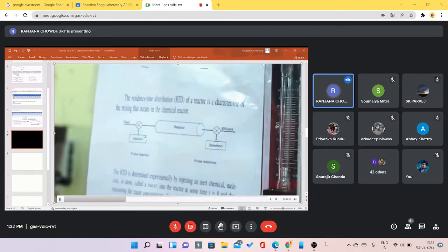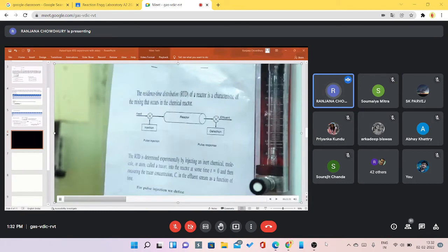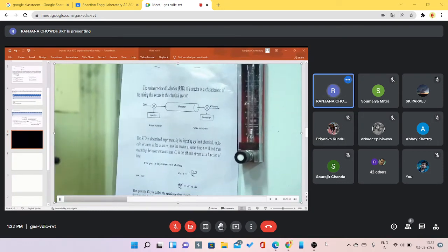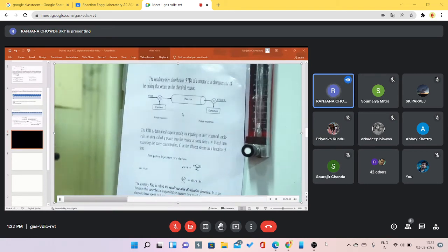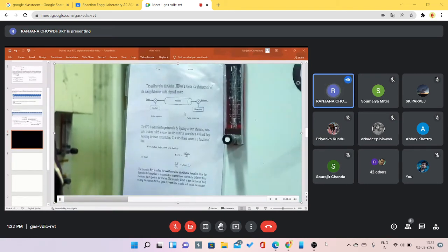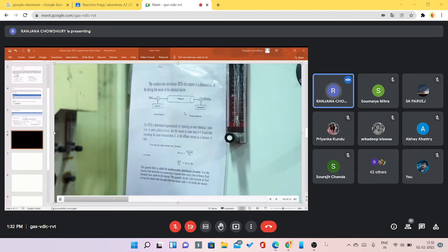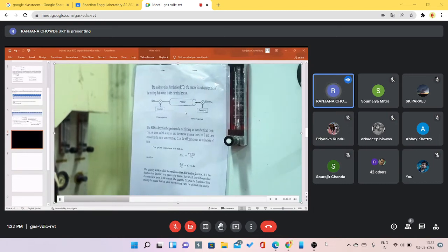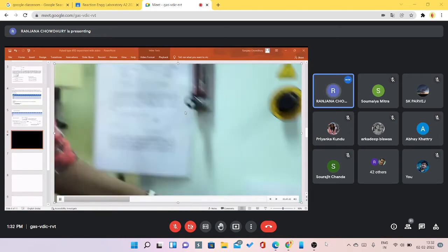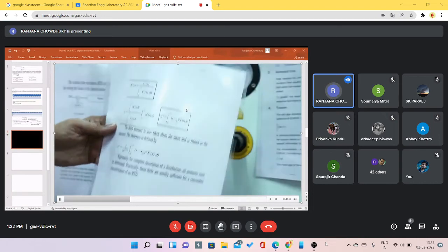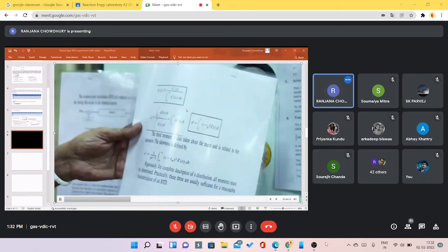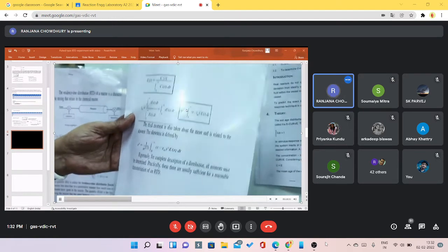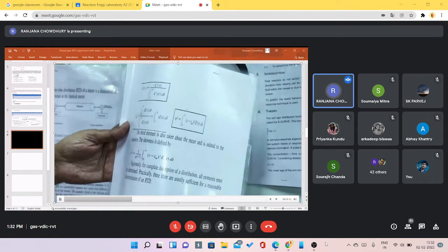This is actually the equation. E(t) is actually v C(t) divided by N0, where v is the volumetric flow rate, C(t) is the concentration with time, and N0 is the amount of the tracer which has been put into the system in the pulse mode. So you can see that you can determine E(t) from this. That is, E(t) is C(t) divided by the integral of C(t) dt with the limit 0 to infinity.